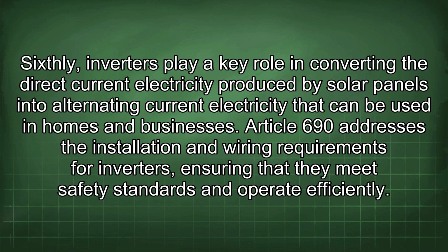Sixthly, inverters play a key role in converting the direct current electricity produced by solar panels into alternating current electricity that can be used in homes and businesses. Article 690 addresses the installation and wiring requirements for inverters, ensuring that they meet safety standards and operate efficiently.